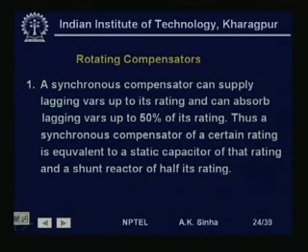So, a synchronous compensator can supply lagging vars up to its rating, that is, up to its designed capacity. By over exciting this synchronous machine, we can supply a large amount of lagging vars, and by making this machine run under excited, we can absorb the lagging vars.